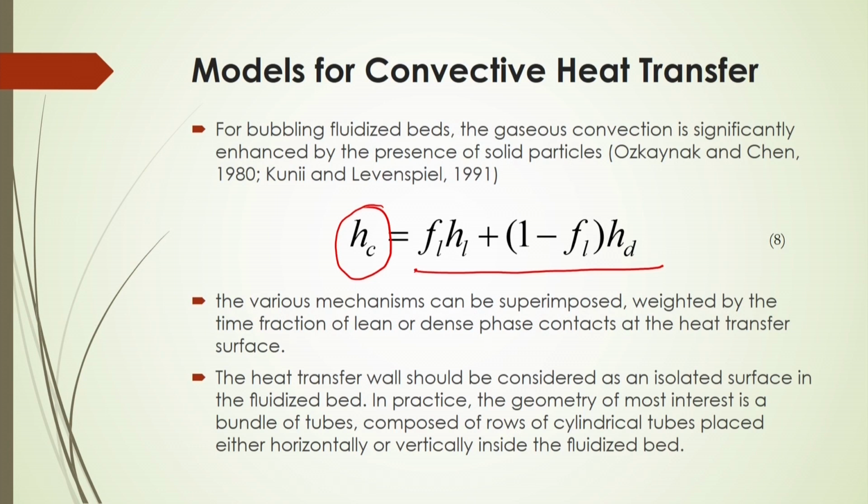The various mechanisms that we have already discussed may be superimposed, that is, weighted by the time fraction of the lean or dense phase contacts at the heat transfer surfaces. Now, the heat transfer wall should be considered as an isolated surface in the fluidized bed.